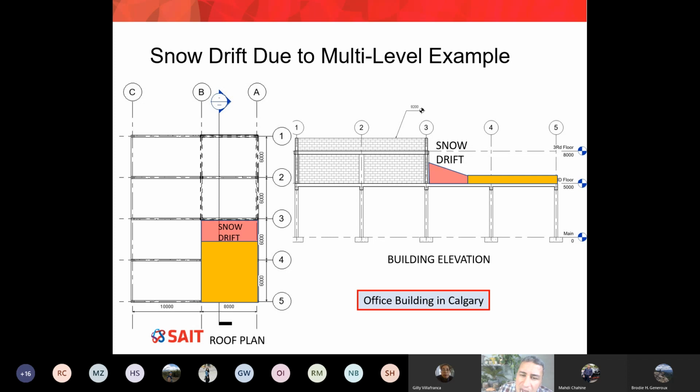But before we do that, guys, the whole calculations will probably take the next 10 minutes or so. Really, what we're trying to do is this. You see the load diagram of my cross section in two colors? Do you see the load diagrams in two colors in my section? My objective from now until we finish this problem is to simply find the snow drift diagram on the lower roof. But I want to say something very important. You will see we will do a lot of calculations, but all the calculations will only focus on the lower roof.